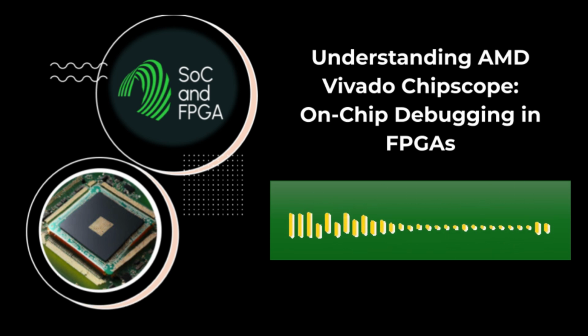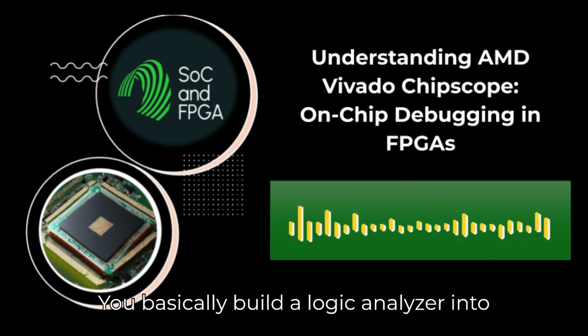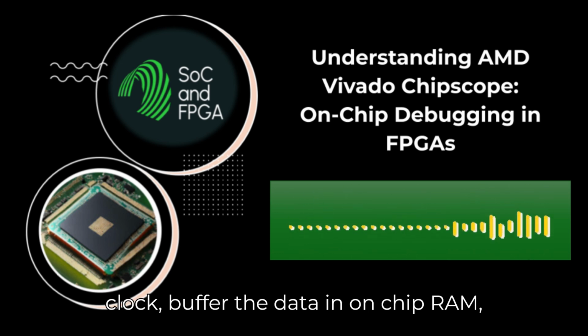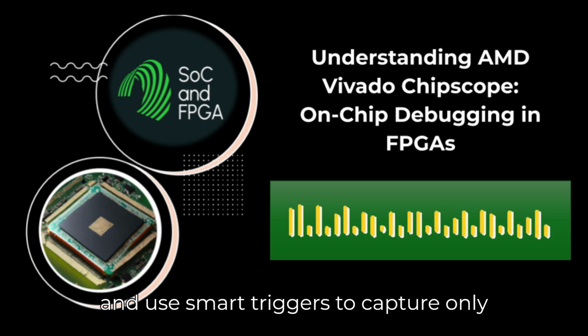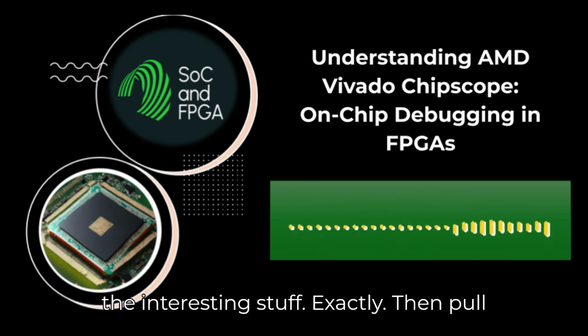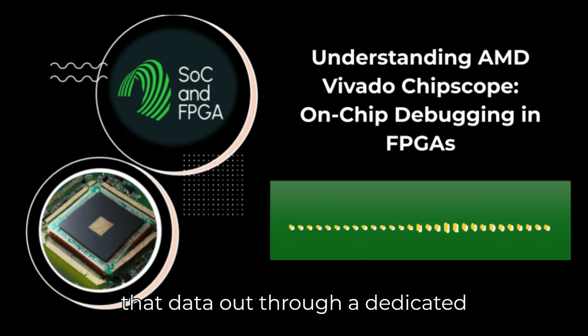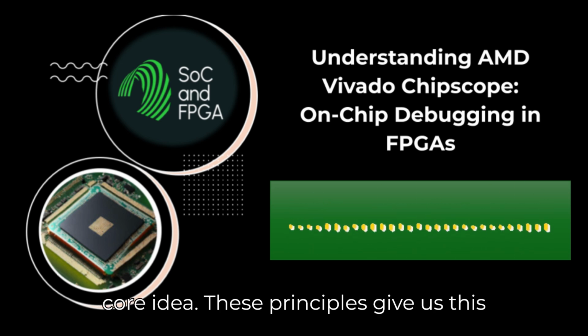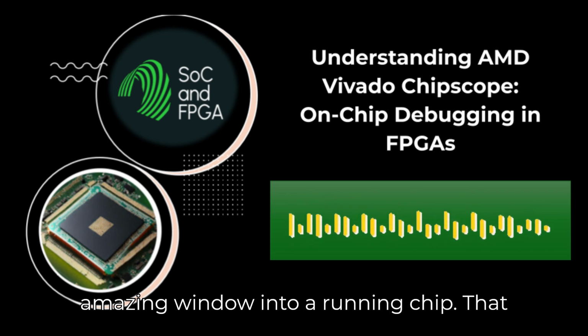Okay, so let me recap. You basically build a logic analyzer into your chip, synchronize it to the design clock, buffer the data in on-chip RAM, and use smart triggers to capture only the interesting stuff. Exactly. Then pull that data out through a dedicated channel. That's the core idea. These principles give us this amazing window into a running chip.